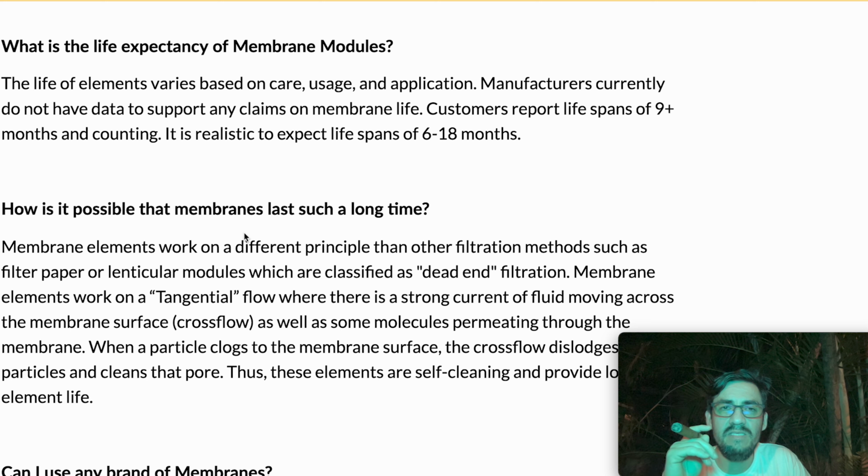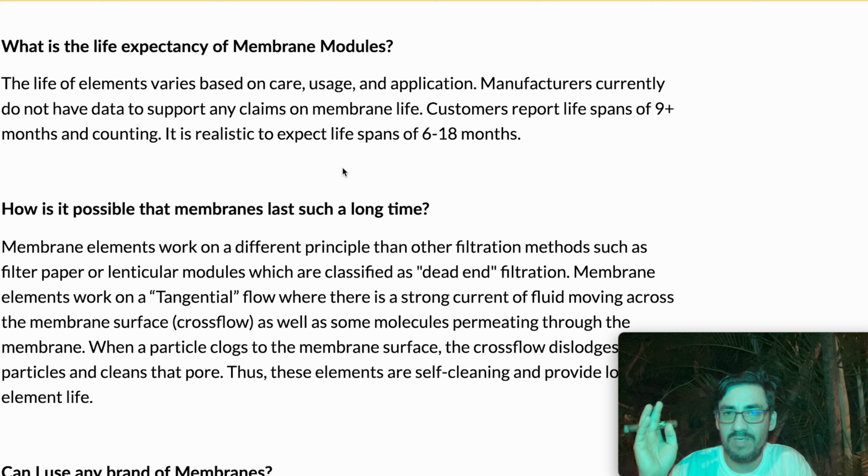What's the life expectancy of membrane modules? So there is no research. If you call the manufacturer of these membranes and say, hey, listen, how long does this last? They got nothing. They're not going to be able to give you a straight answer because there is no data to support it. What I can tell you is that on the membranes that we've placed out in the market, you can expect somewhere from 6 to 18 months of use.